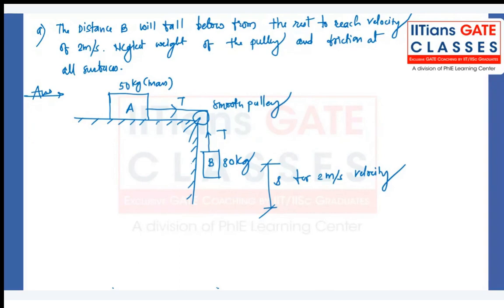It's not that difficult. Wherever distance is mentioned in the problem, you have to solve with the work energy principle. Whenever acceleration is to be calculated or involved, you have to use D'Alembert's principle. And wherever time is mentioned, you can think of the impulse momentum principle. So this is the basic logic you should know. If distance is involved or supposed to be calculated, use the work energy principle. If they are asking you to calculate something related to acceleration, D'Alembert's principle will help you. Keep this trick in mind, so in the exam you are not confused about which method to apply.